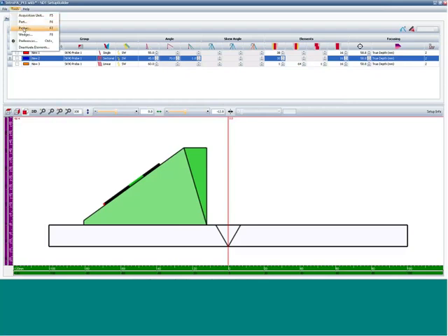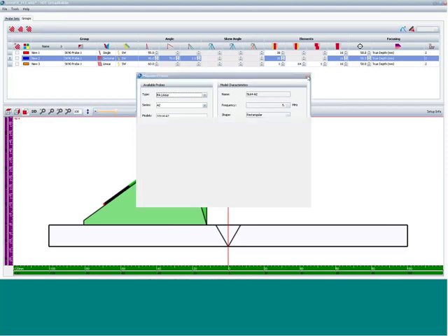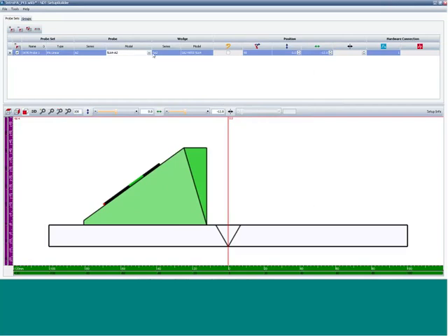Under the probe tab, we have similar information as the OmniScan database, and we can manage this directly here. Probes are added or removed, can be cloned and copied in reverse position directly on the interface. So this is a linear PA probe. TOFD and UT probes are also programmable. From the A2 family, it's the 5L64.